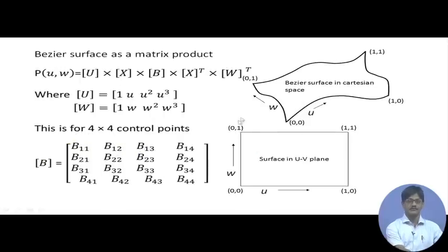So, similarly if we look at the formula of the Bezier surface, it looks this way. The Bezier surface has this u parameter varying from 0 along the edge up till this point where it takes up a value of 1. Here also, along all these lines moving from this side to that side, the u value takes up a value of 0 at the start and moves along, increases its value and ultimately reaches a value of 1 here.